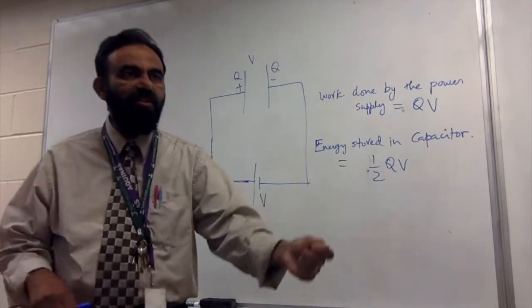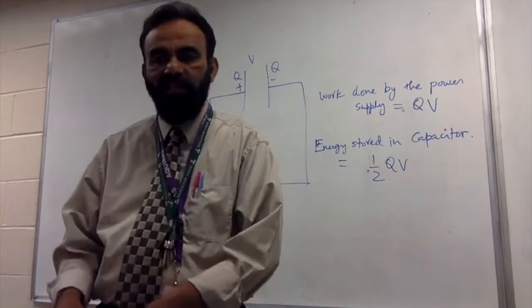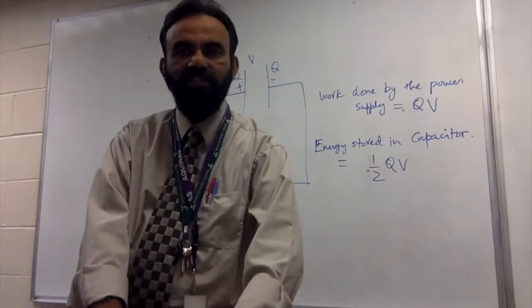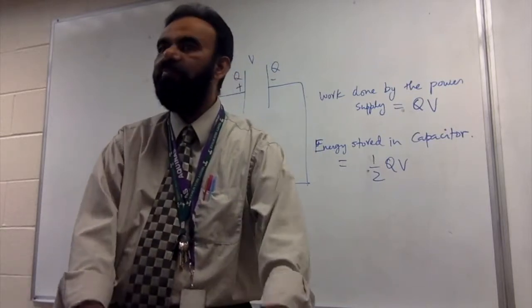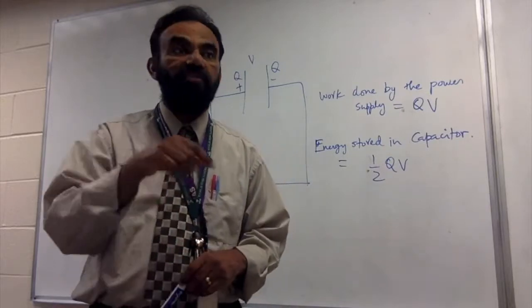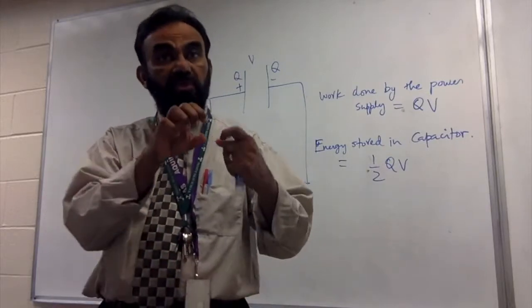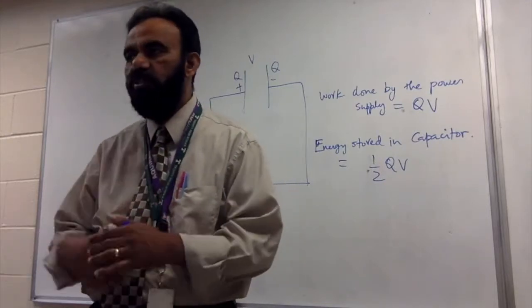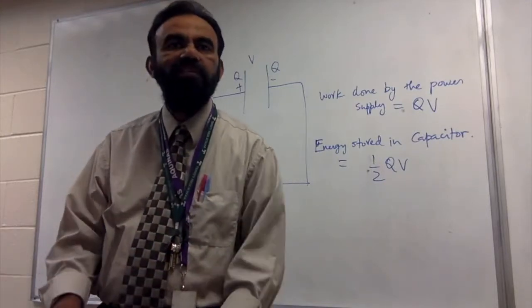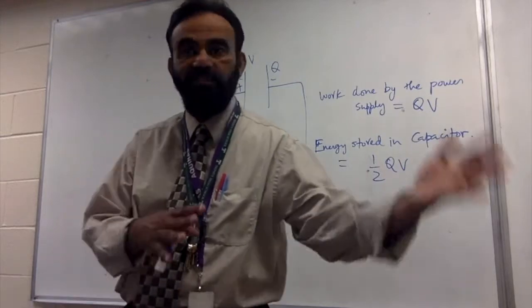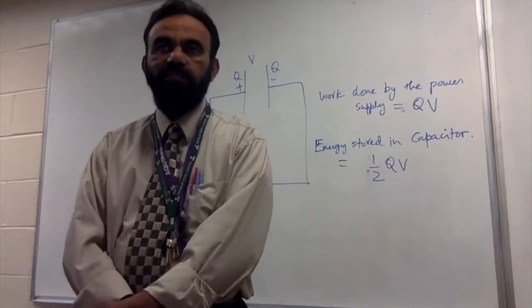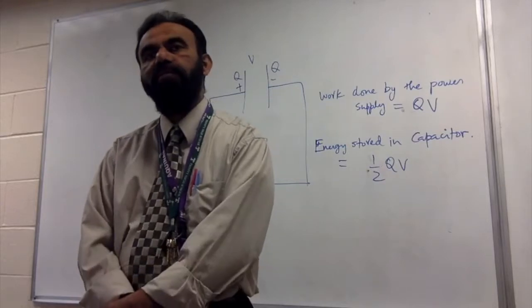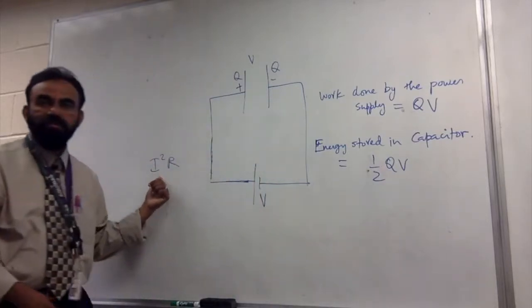You put an extension cord and then you connect your computer or whatever, and after some time just touch the extension cord and you'll see it's pretty warm. That is heating effect of the electric current. Now try to take a thick cable, very thick extension cord, you will hardly feel it getting heated up because there is less loss in the wires, and the loss depends on this.